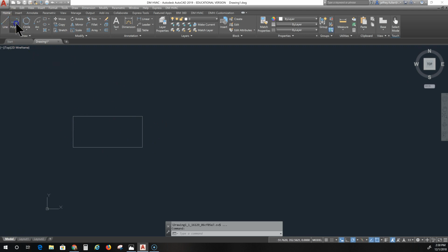However, if I click on Polyline and draw a similar rectangle, it's all one unit. I can click on it to select the whole unit, but if I click here on the separate lines, I just select one line. On the polyline, it's all one unit. And I can use these little grips, if I use them correctly, to alter the shape. And it will ask you this on the test.